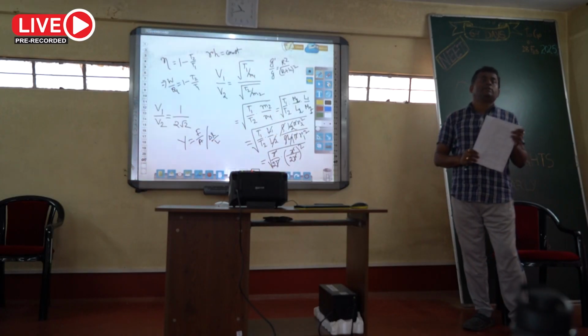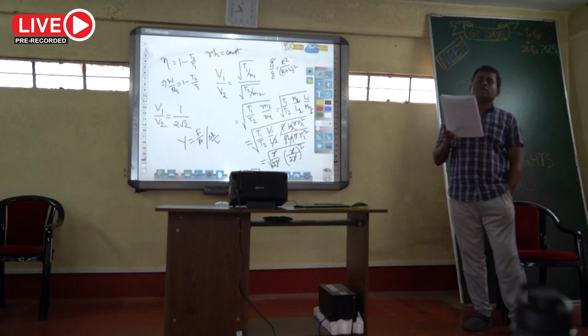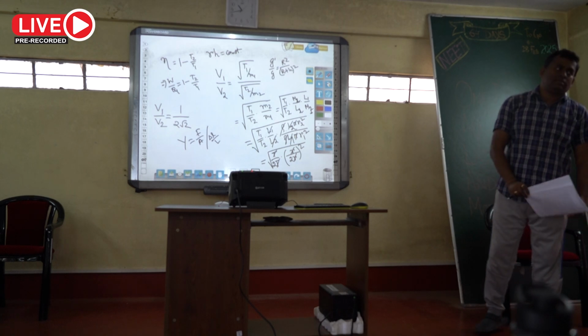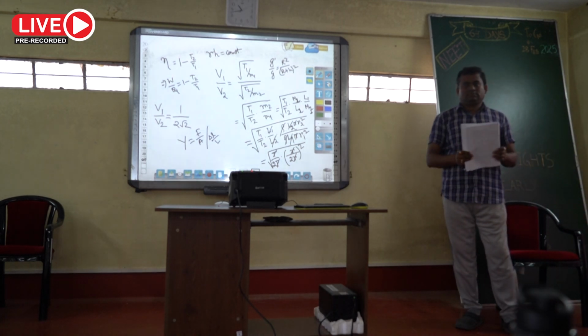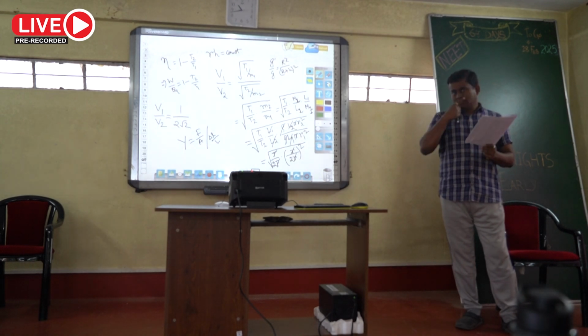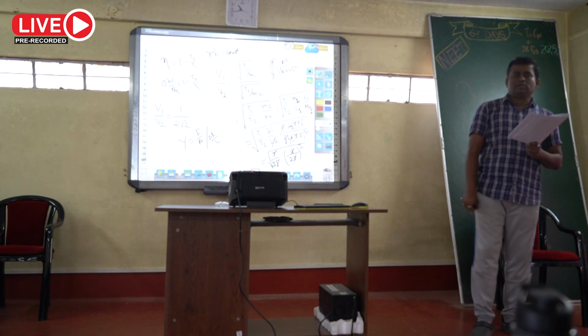The product RH will remain constant. So when the tube is replaced by a tube of half diameter, meaning the radius will be half, then accordingly H will be doubled, such that the product RH will remain constant. Diameter half means radius also half. So to keep the product RH constant, H should be 2H.